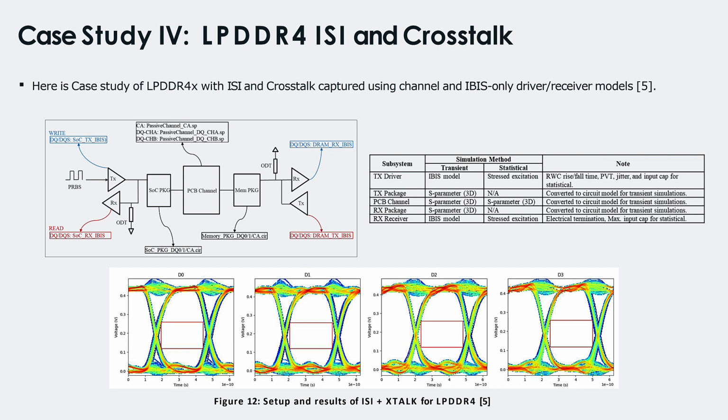And Ashkan is here to show one such example for LP4, where we did only an SI-only simulation and its impacts. Yeah, I think we are running out of time, so I'll make it quick. So this is basically just showing that there will be a case where we, as a channel designer, are supposed to design a channel without being aware of what kind of models you're going to get from your RX or TX. So you're in an environment where you would like to stress test your channel, but at the same time, in the future, you want to make sure that it's going to work with different mix and match of driver and receiver.